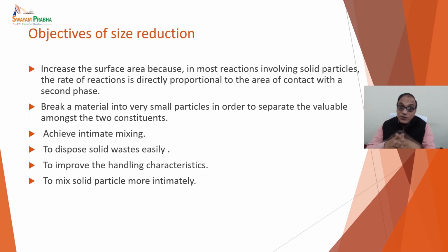We do the size reduction for achieving the intimate mixing, good mixing, to dispose solid waste easily, and to improve the handling characteristic. We do the size reduction to mix solid particles more intimately. More intimately we can do the mixing process, and that is utmost required in all the pharmaceutical industries, because we have to make a uniform blend of API with the excipients. So many kinds of blends are needed to be prepared. So that's why the size reduction has got the importance and wider use.